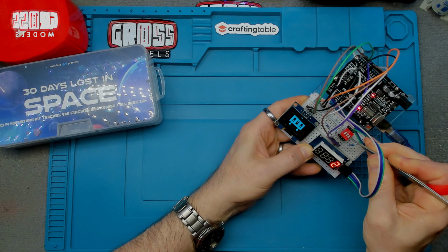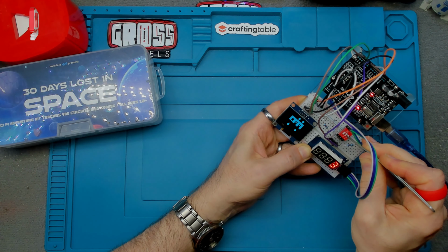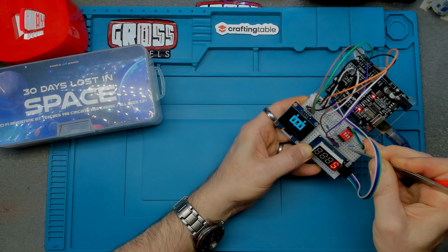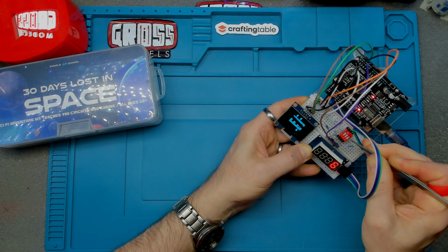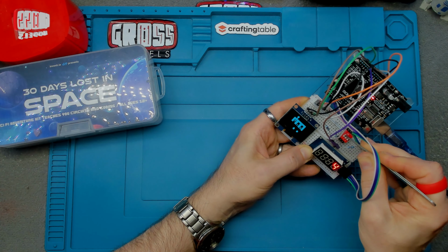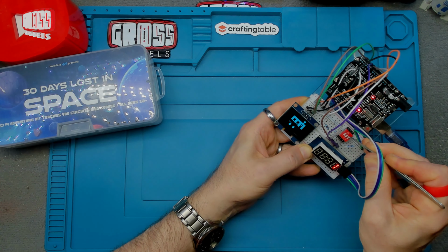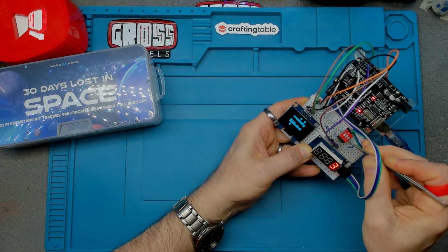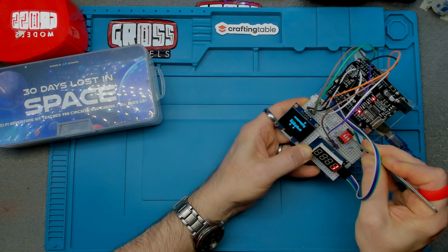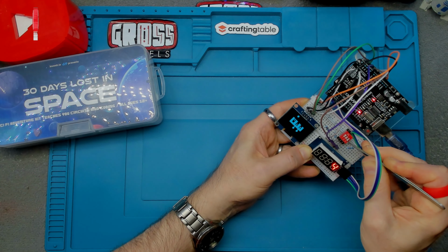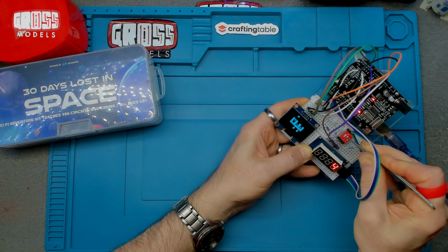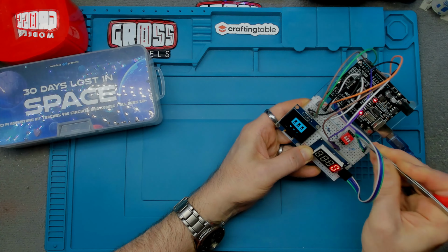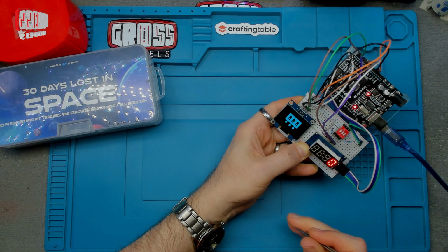Yeah. So I understand how that works, and we get a graphical representation of what the dip switches are actually doing, and a numerical representation of what it is. So we've got 1, put that back down to 2. That one up is 3. Now to get to 4, we need to put both of those off and that one on. Then we've got 5, and then just that one there, 6, and that is 7. So we've got all 8 switches giving 8 different views on our bitmap down there.